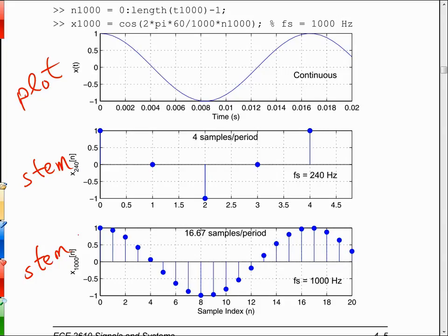weeks back I was talking about plotting sinusoids, and remember we discussed how many samples per period would make the picture look good. I think we concluded that 10 was kind of coarse looking, 50, maybe even up to 100, no problem because MATLAB can handle it. But when we talk about sequences and actually wanting to consider sampling theory, we don't need to be in the business of overkilling, because that just means that we have more samples per second to process, and the computer, the embedded system that's going to work on it, is going to have to work harder.